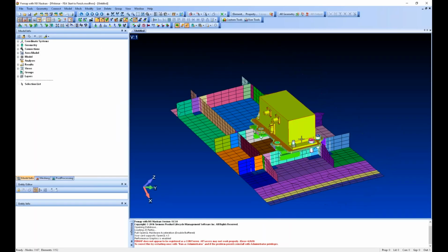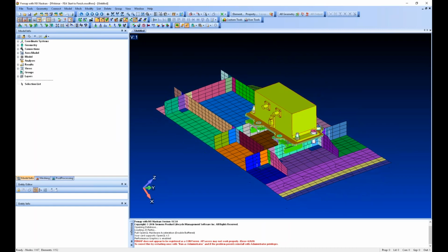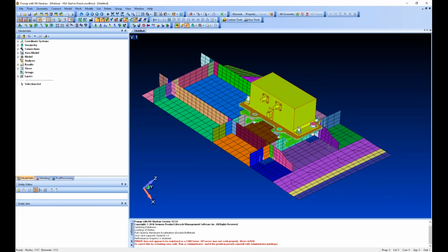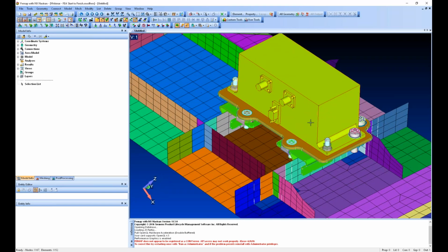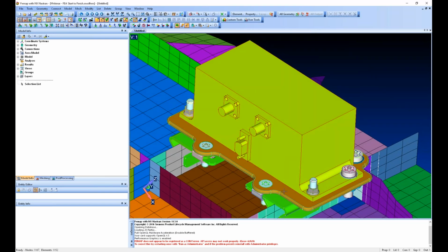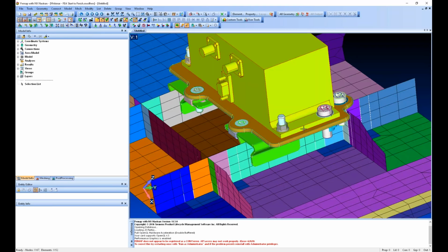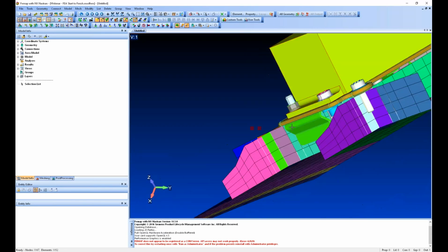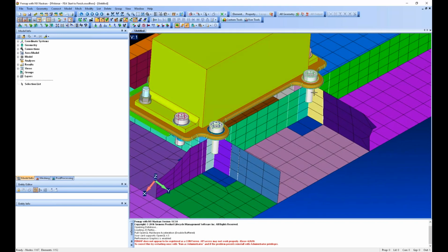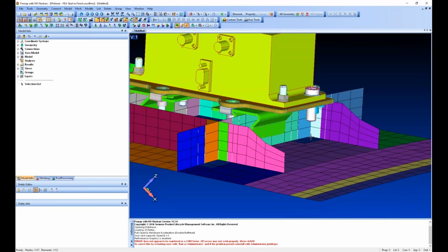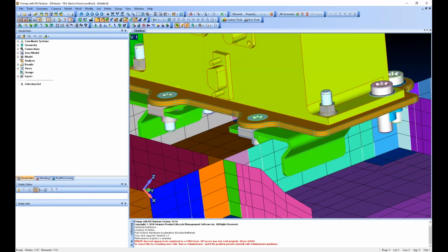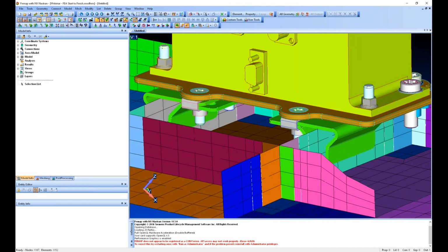So here's our starting model in Femap, and you can see the pressure vessel has basically already been meshed. So let's say this is an existing FEM that's already come out and is working, and now we need to analyze this subcomponent that's mounted to the exterior. You can see we've got a box that's connected to this brown adapter plate by 4 bolts, and then the plate connects to our orthogrid panel with 2 bolts here going directly into nodes of the orthogrid panel. And then there are these 4 green brackets which are actually bonded to the ribs of the orthogrid panel.